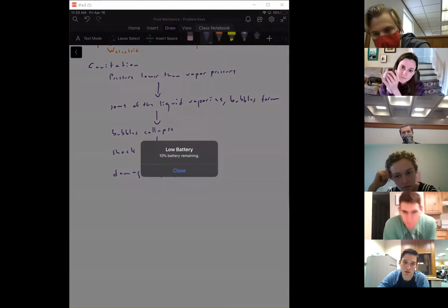In reality, it isn't exactly 0, because in the first tank the water level is dropping, so there is some velocity. In the second tank the water level is going up. So technically there is a velocity at that surface, but because the surface is so big, it's dropping really, really slowly compared to everything else, so the energy from everything else is going to be really big. And so we just say it's about 0. We make that assumption all the time.